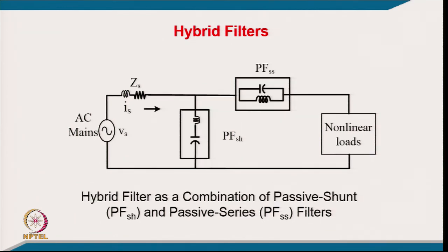In this case it can be done in the reverse way also, but certainly this is not so attractive, because this will be good only for a voltage fed kind of load, as this will block and behave as an inductive circuit. So this can give reactive power and it can suck some of the harmonics, but certainly its popularity has not gone so high. We will discuss that also, how it really offers a good combination. So this is another hybrid filter.